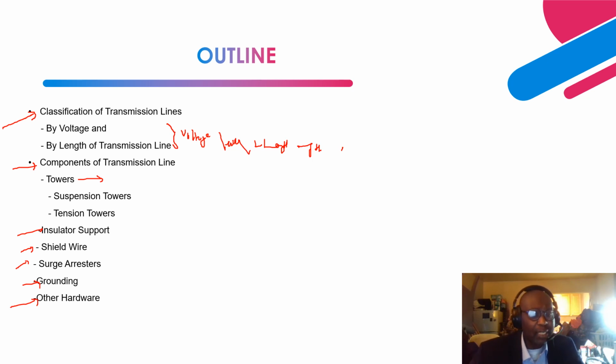Another hardware that we'll talk about is spacers, right? Sometimes, based on the amount of current, if a phase current is so high, then bundled conductors are put together per phase. A typical example is you can have 4 conductors bundled together in one phase, right? If you have 4 conductors in one phase, you need something that is going to keep them rigid in space, preventing each conductor from clashing into each other due to the wind.